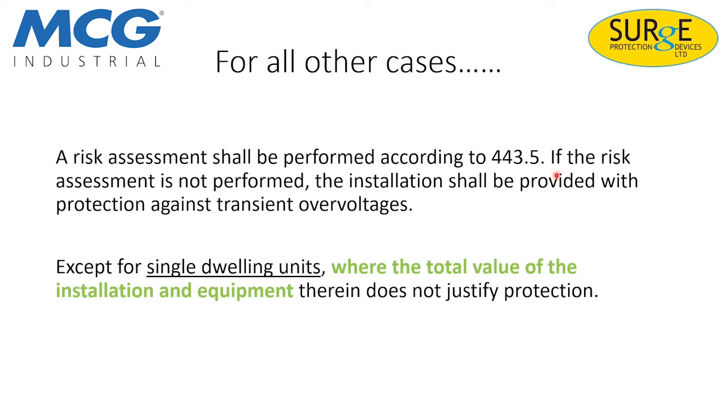As an electrician, it's very, very hard for you to make that decision that the total value of the installation equipment doesn't justify protection. So what's recommended here is you discuss it with the client. Recommend surge protection if you're putting in a new consumer unit. If your client doesn't want it, record it on your installation certificate that you recommended surge protection, the client declined. This will stop any issues further down the line if your client has any damage. It will just give you an added layer of protection for your personal indemnity insurance.